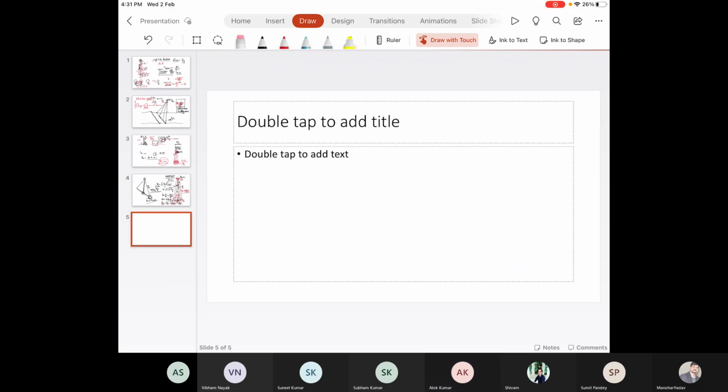Sir, on the basis of the equation which we derived, I can say that if we are flying above an adequate height, then there will be less accuracy for the point data collection. And if the point data collection is less accurate, then we'll have to fly again and again to take the data. Like, sir, in a situation like tropical rainforest areas where the trees are very high, we cannot have accurate data because of the height variation from the ground level. From those places we have to fly again and again to get accurate and overlapping data.